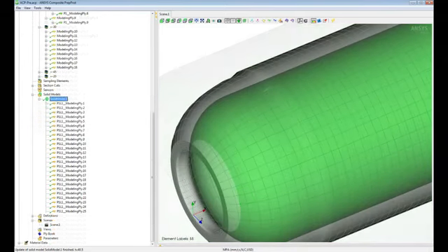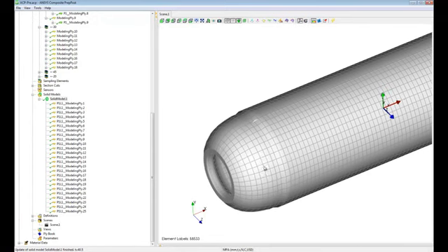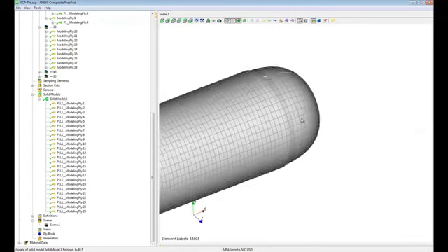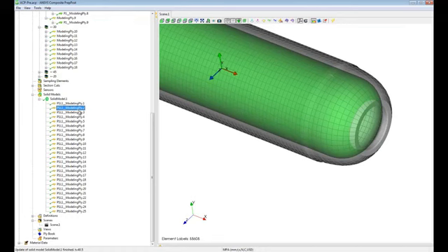So we are using a couple of geometric guides to make sure that we follow the given geometry, and we are extruding all the plies to create a 3D model made of X elements and some wedges in the drop-offs, that we are going to reuse when we assemble them with the caps that we have defined in this second model on our project page. And here you can review each and every ply within the 3D model, obviously, as you could do on the shell model.